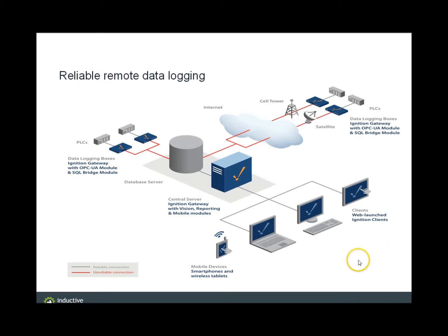This architecture is used a lot in water, wastewater, oil and gas, but basically it's where you're connecting to devices that are out in the middle of nowhere. They're kind of unmanned, and usually people don't go out there, but you can install, if possible, a little piece of the software which is called the SQL bridge. So that would be loaded at these remote locations, and then you could have a main central server with a full Ignition software bundle on it.